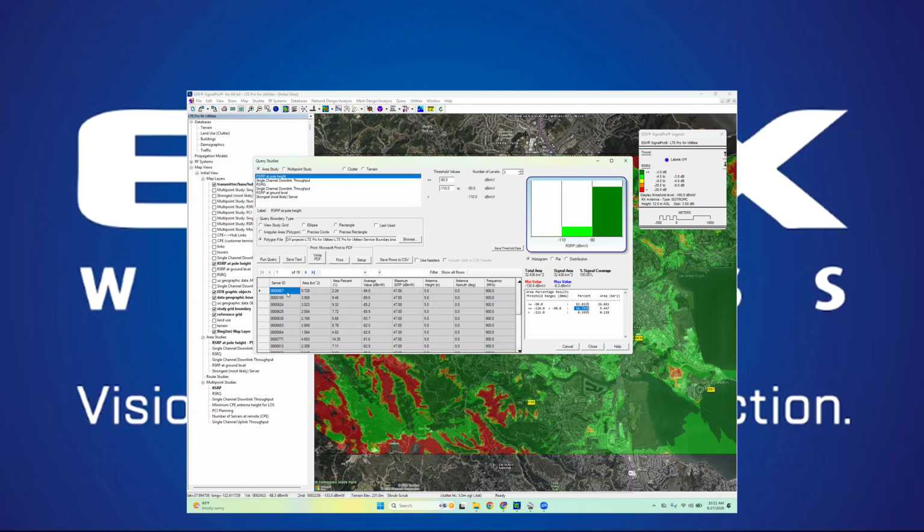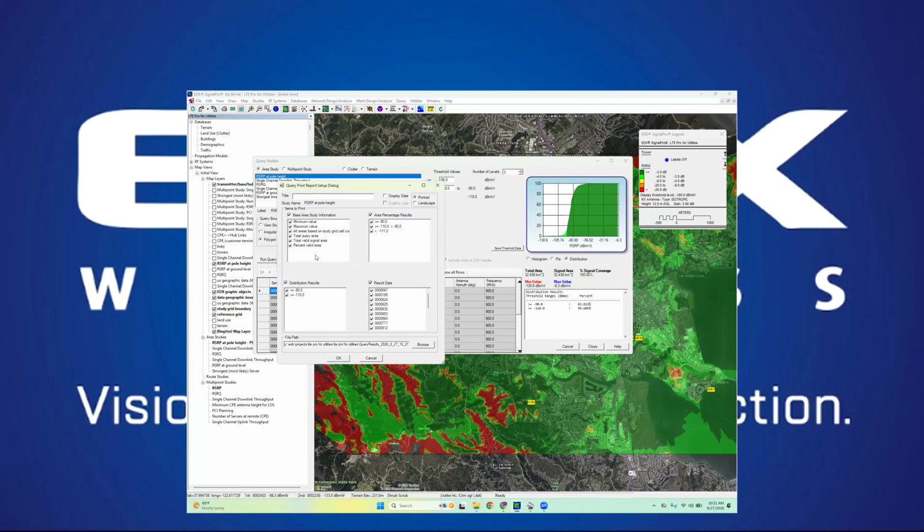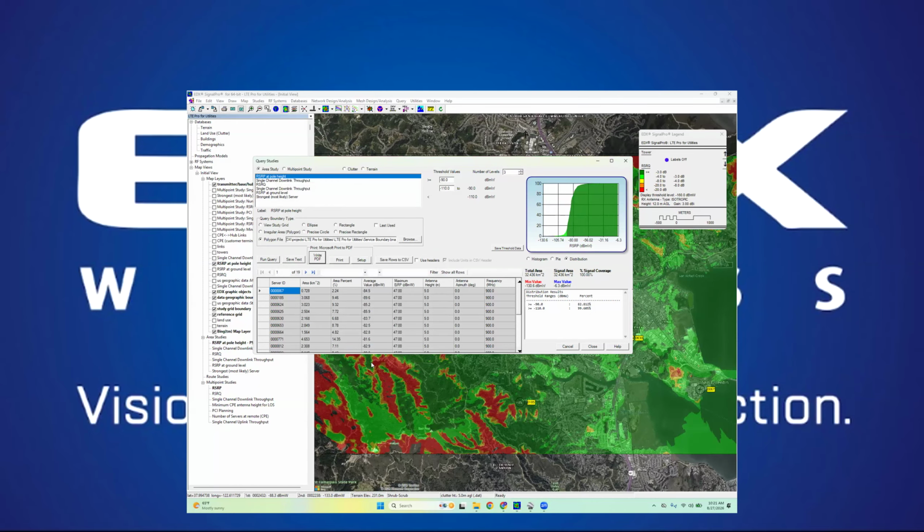Over here on the left, we've got a table that gives each sector's overall contribution where it's the strongest server for that area. And if we want to, we can export that table out to just a simple CSV file. And by the same token, if we want to see these charts or my distribution here for the area study, I can use this write PDF tool, and I have a nice configurable tool here that'll write these graphics and these results out to a PDF for me.